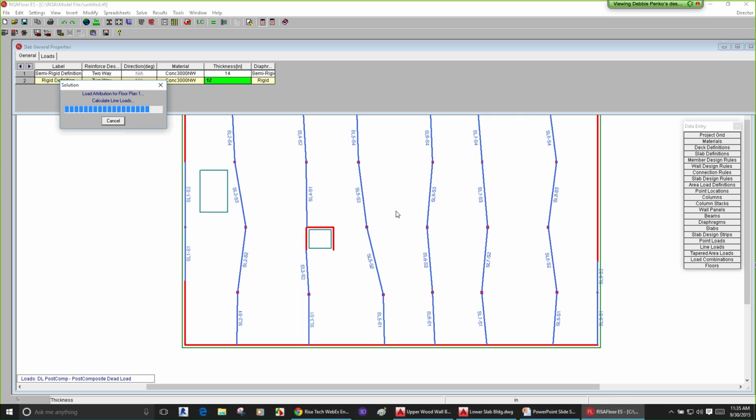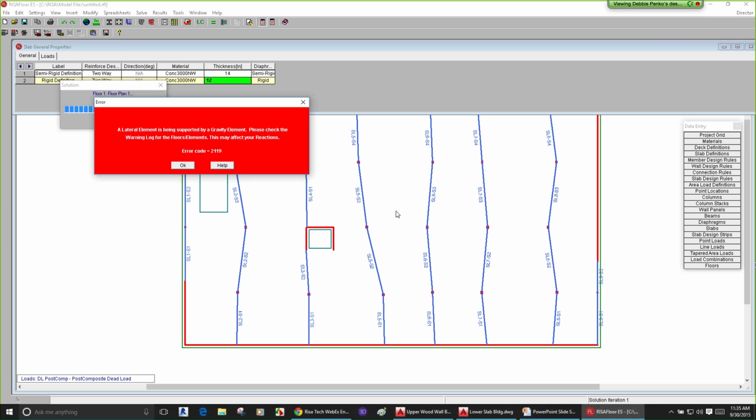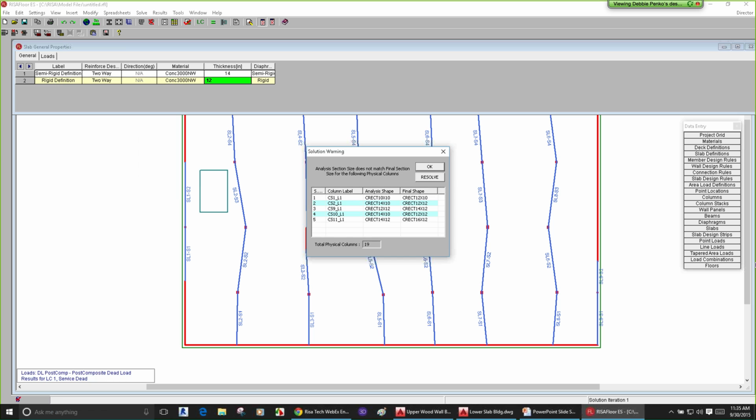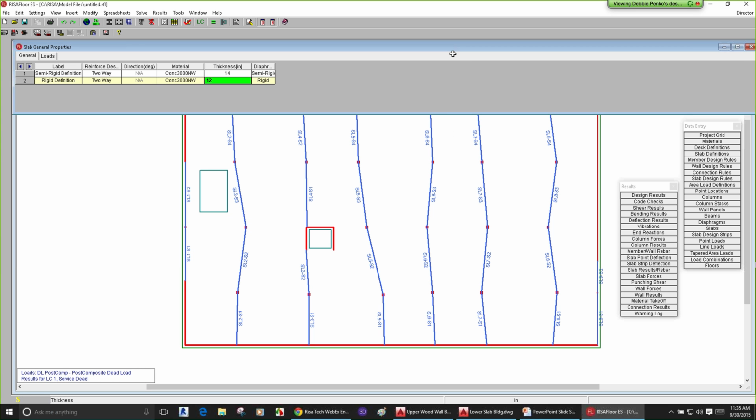We're also going to talk about shear caps. So maybe the punching shear is still an issue. We can take a look at what to do there. So we rerun the entire solution because you don't just thicken the slab. You're changing force distribution throughout that whole slab. So the wood structure sitting above it is going to be distributing it differently based on how it deflects, things like that. So go ahead and see.